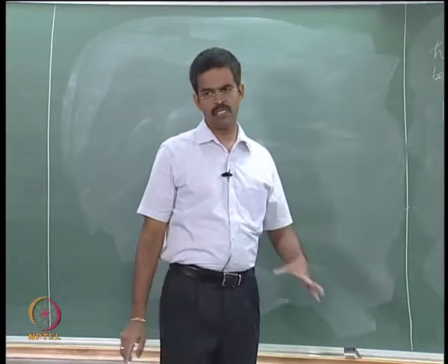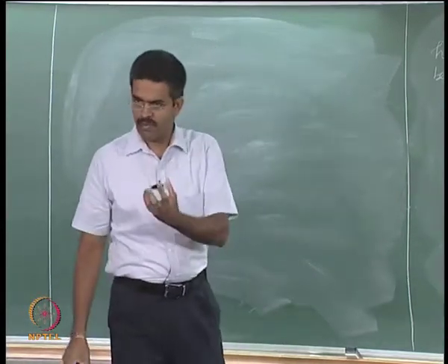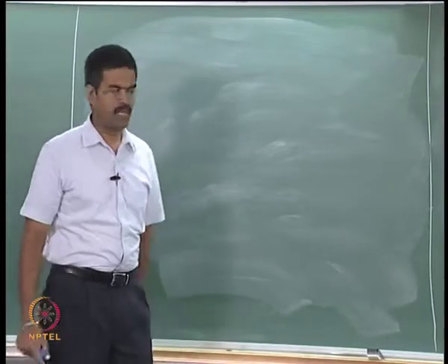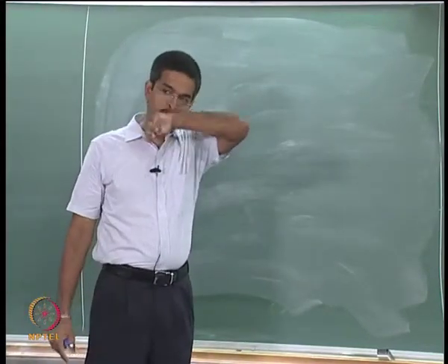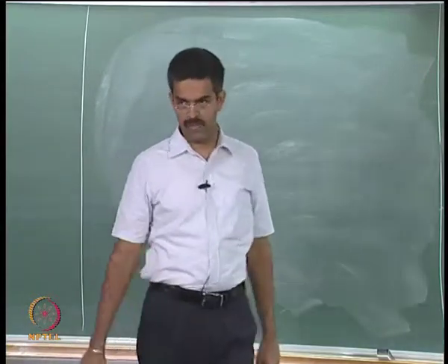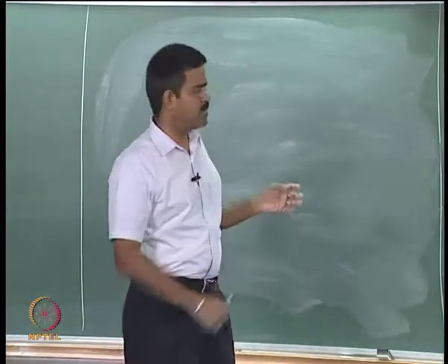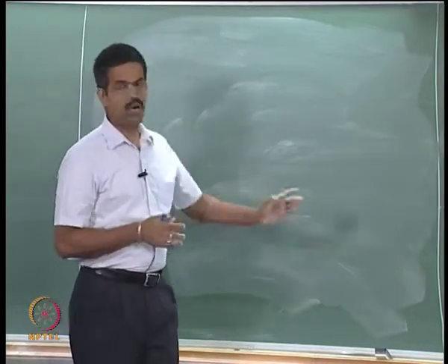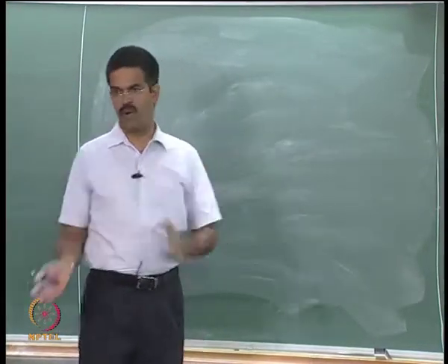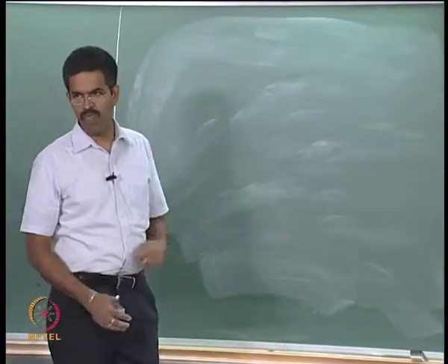So, the moment I say it is expressed in probabilistic manner, it should give me a number. So, MR and MS, that is mean value of the load and mean value of the resistance, will not have any significant meaning unless otherwise the two curves are expressed slightly in a different form. Let us see what is that form we are looking at.